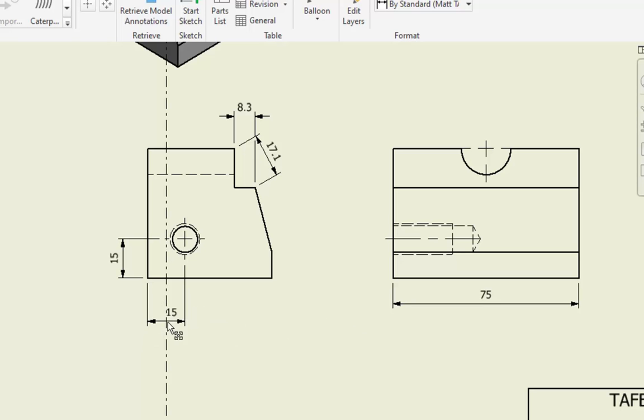So you can actually pull the text out and all that sort of thing. It'll still snap back to the center, all right? But if you want it to line up with another dimension, just drag over, pause on the other dimension there, and it'll give you that line, and it'll give you like a magnetic snap, so you can drag it back and release it in the correct position. Alright, so that works on the same view very well, and it also works across views as well. So that's just a little trick to get dimensions more readily aligned.